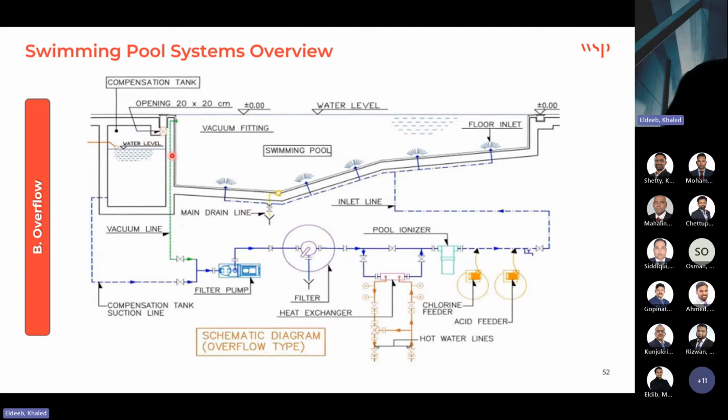Yeah, as I told you, this balancing tank is usually provided in public pools, like in ultra luxury hotels. Actually, most of the pools today, like this one, are not skimmer type. This one should be maintained by a proper team on a regular basis. Not only the tank, the filter also might get clogged. Maybe the pipe is corroded and it will get broken. So this entire system cannot be left alone working.